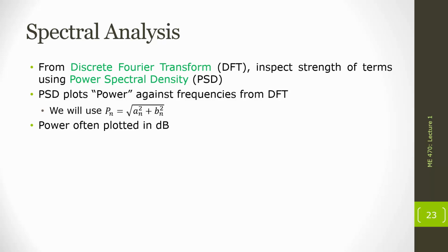For time series that are long, where we have lots and lots of samples over lots and lots of periods, there are going to be better ways to smooth or filter our data. So I'm not going to be talking about more advanced methods for doing our PSD, which is things like windowing, where we're taking small subsamples of our time series and then basically averaging them together. And this is going to be good if we have noisy data, where on average the high noise and the low noise are going to average each other out. That's what windowing is going to take care of.